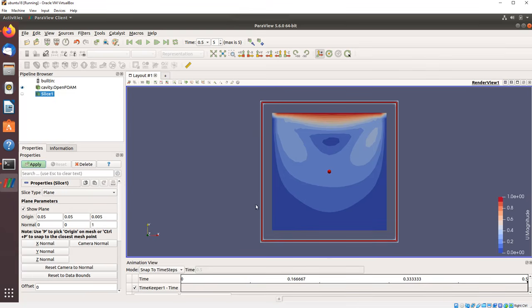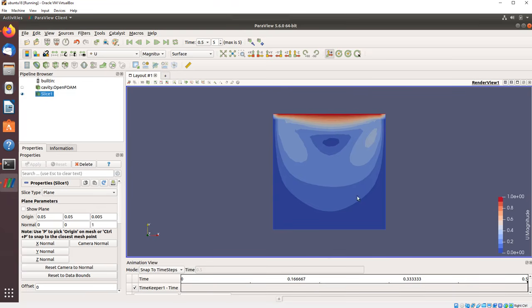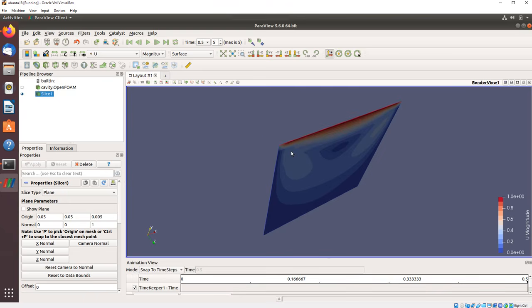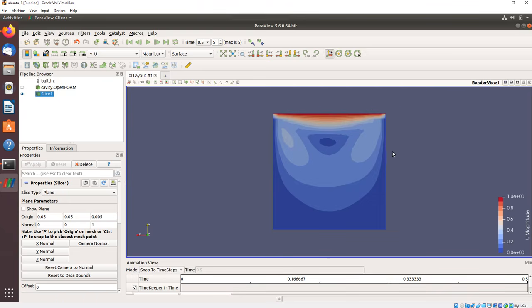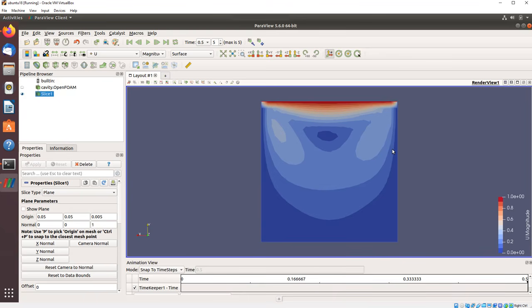square goes into this plane, and I click on apply, and now I actually created a second view, which is a filtered view along the slice. Because I'm not interested to see this, again, I can hide this cutting plane. If now I'm rotating the model, you see that now I have a 2D model. That's what I wanted. So I'm ready to go for the next kind of post-processing.